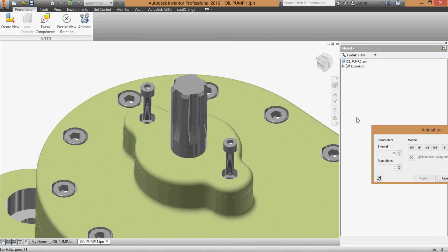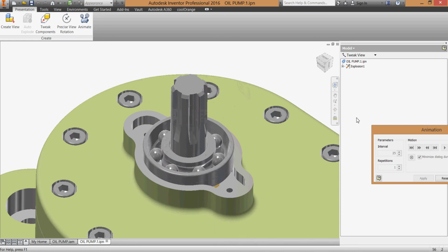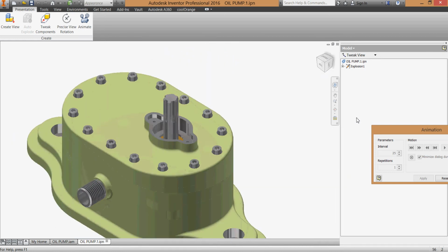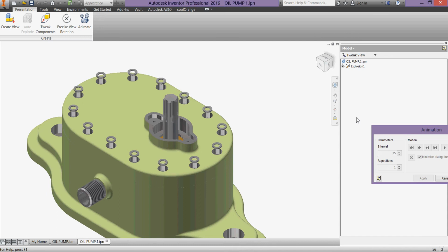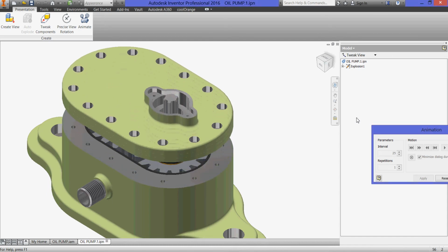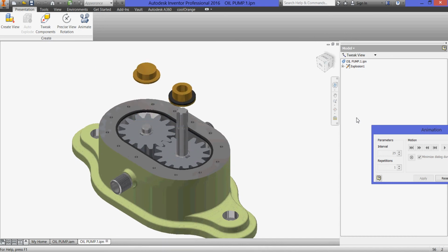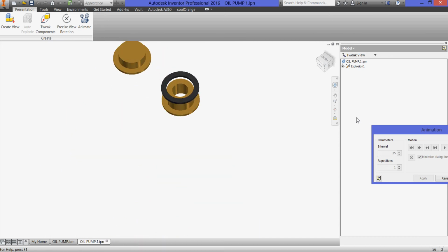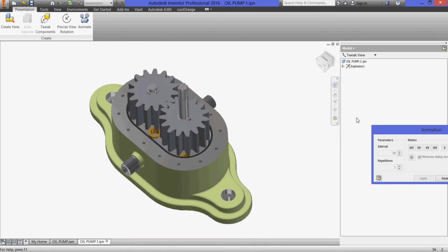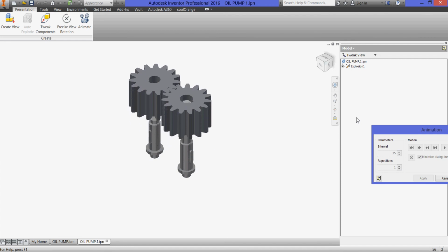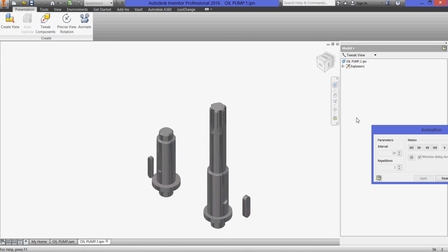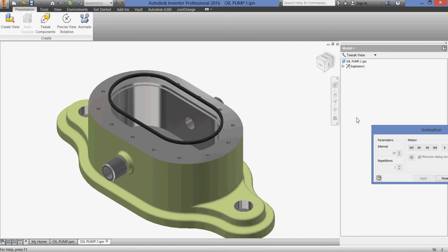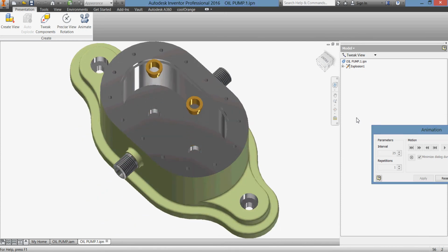So we'll unscrew these bolts or screws, taking these washers, and step by step what are we doing? Unscrew bolt or screws. I'll take the washers out, taking the cap, and then the upper bushes, taking the rubber from this bush, taking out my gears with the shafts. Now my keys are out, and we'll take this rubber out, and at the end we'll take these two bushes.